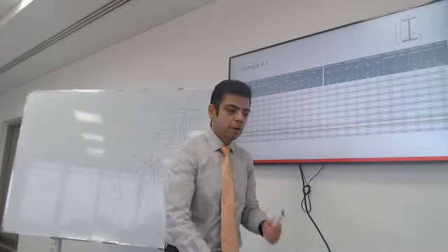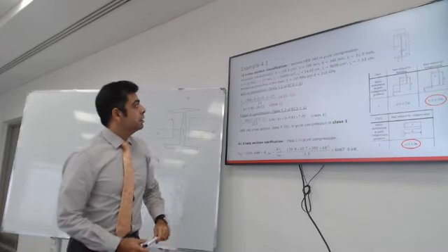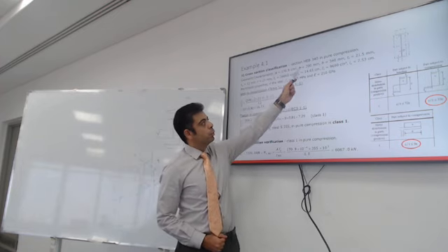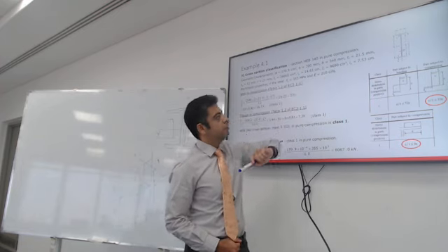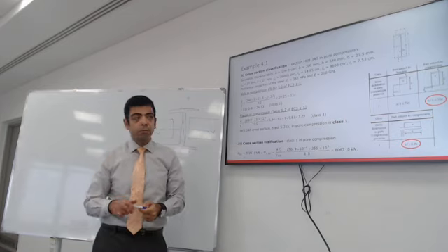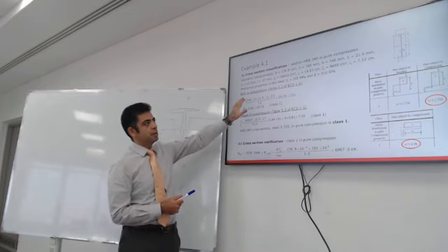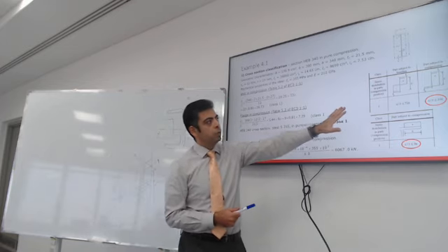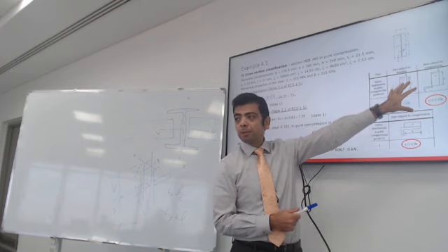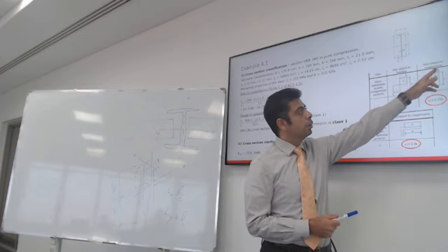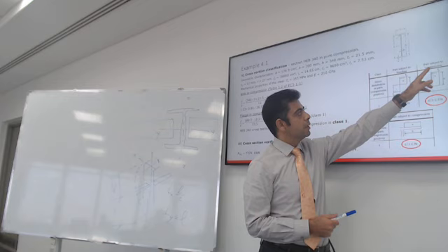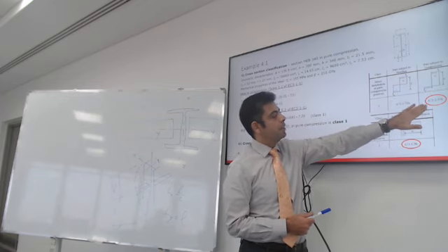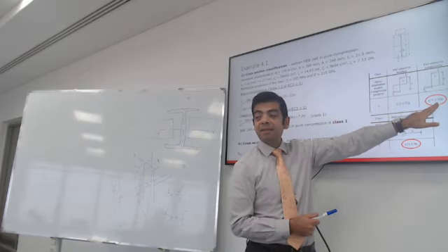All right, so here is the summary of the cross section. That's the area, the width, the height, the thickness of the flange. We got that from the commercial tables. Let's check the assumption. Let's assume it's class 1. So we'll go into the code table under pure axial compression, parts subject to compression, and make sure that the ratio c over t is less than this magnitude.